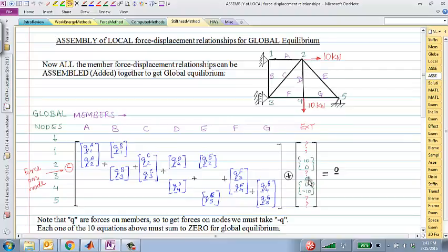Similarly, there is 0 in the y direction here. There is 0 and minus 10 on node 4. That also makes sense: nothing in the x direction, minus 10 in the y. And all the question marks denote the unknown reactions. In this case, I have 5 unknown reactions, so I have 5 question marks, and even those reactions are external forces on the truss.